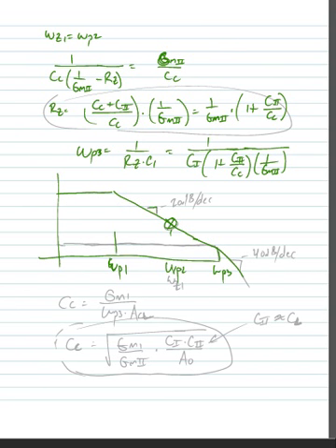So here we have a minus 20 dB per decade roll-off. At the pole-zero, nothing happens because the pole-zero cancellation occurs. And at our original third pole, we get our 40 dB per decade roll-off.